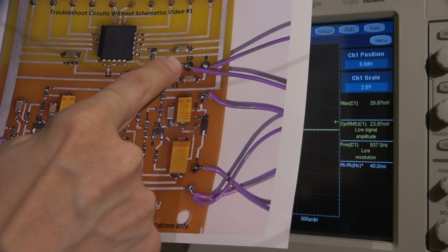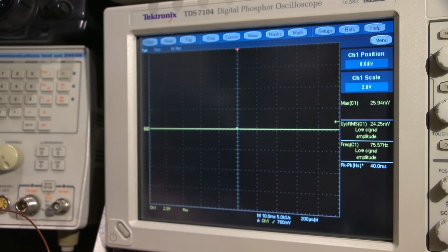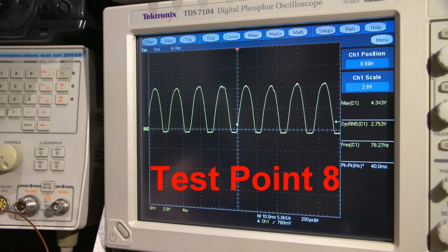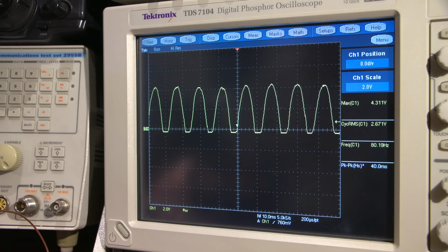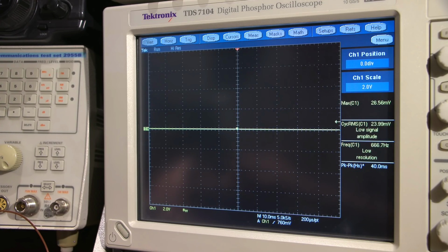So we can verify that the signal is getting to these points here by using our scope. So what I'll do is we'll go back and probe, again, this portion right here. Now what we're going to do is, since we know we're following the wires here, we want to find out if this is getting, because this is now in the intensify position, to the intensified area. That intensified test spot is now number 9. So we go to number 9 and we see nothing is there, but we have to remember to turn the gain control up. So here we go.